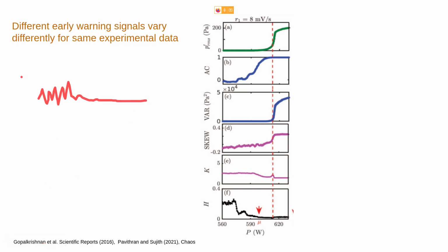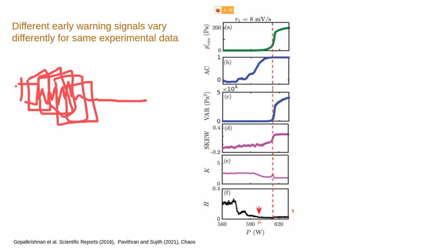Now when you are taking the windows and progressing slowly, you will see that the same time series keeps coming into the different progressing windows. When this happens, you get more and more correlation between each of the segments. So your autocorrelation slowly increases from a smaller value to a higher value, and when you have a sinusoidal oscillation, your system eventually goes to an autocorrelation value of 1.